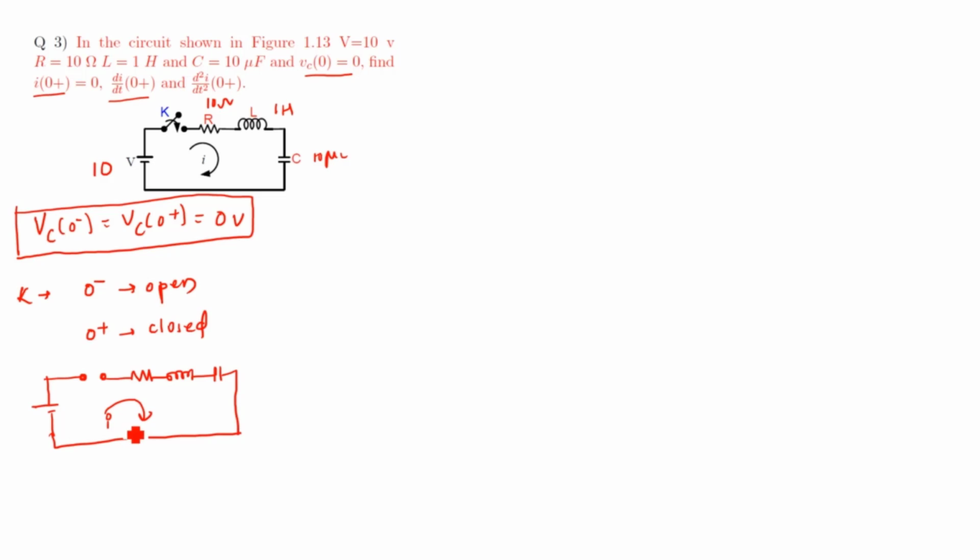This current is I. Is that the current flowing through an inductor? Yeah. Then we don't find any closed circuit here. Obviously the current before switching equals 0. Is that the same current flowing through an inductor? Yeah. So that is equal immediately after switching. It is the property of an inductor.